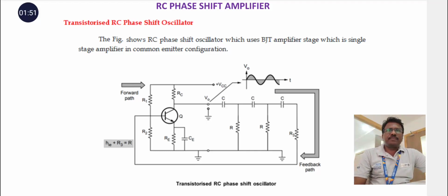Basic principle: every oscillator works based on one important principle called positive feedback. That means a portion of the output signal is fed back to the input in phase. Only then will oscillations continue.